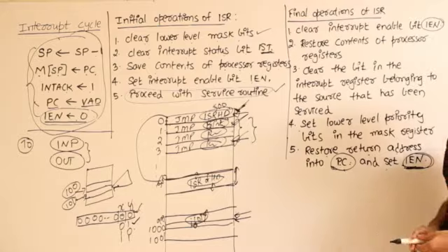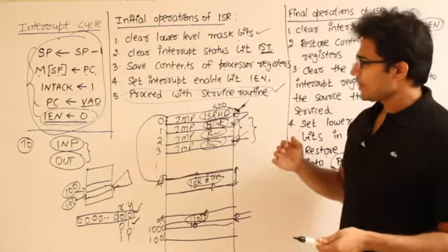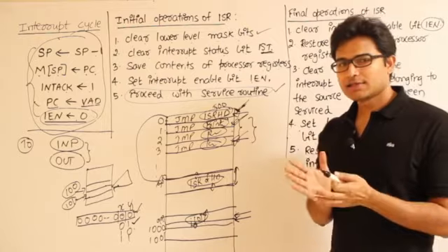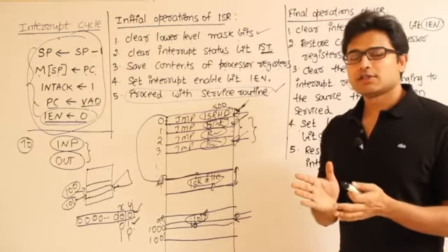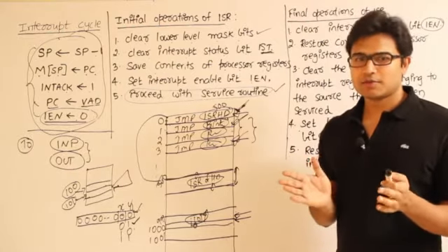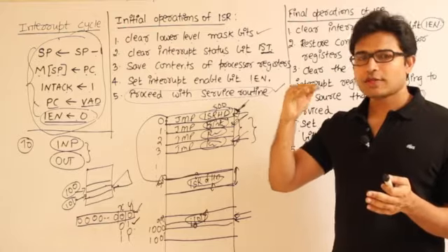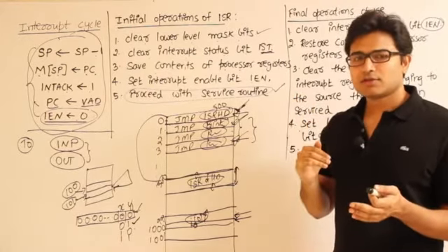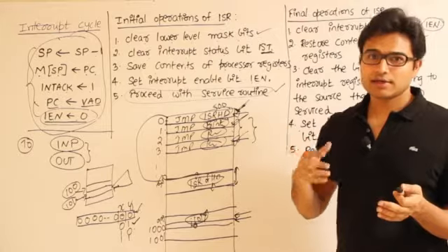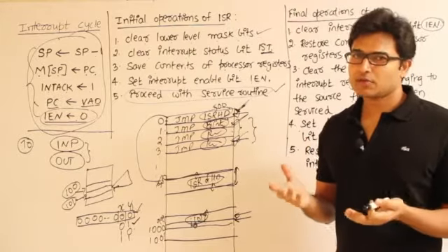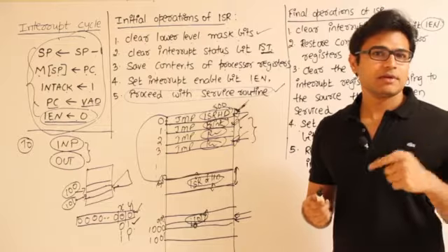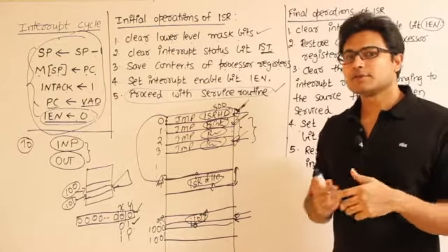So see this. There are certain tasks during which we should never be interrupted, which means when we start performing those tasks, no one in the middle should disturb you. That is generally called atomicity, atomic units. During that part, we disable the interrupts and enable them again once that is done.